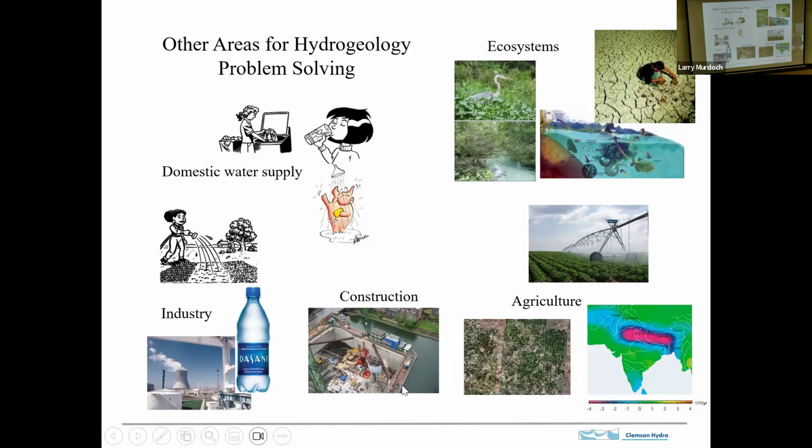This is a building foundation that's being built. You can see that's an excavated, deep pit, and there's this canal right here. So this is a place where water would be a nuisance, and in fact a potentially hazardous situation if that water were to get into this excavation and flood it. So understanding how to keep the water out will also be an important application.